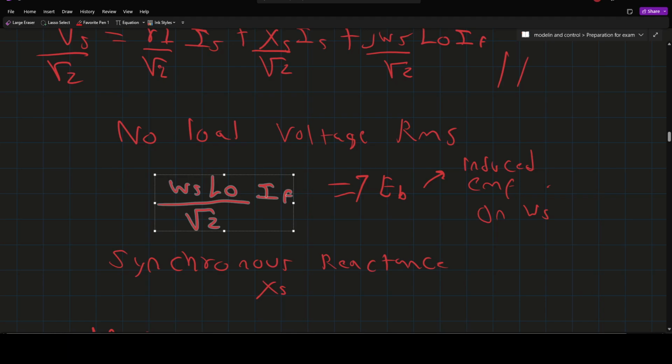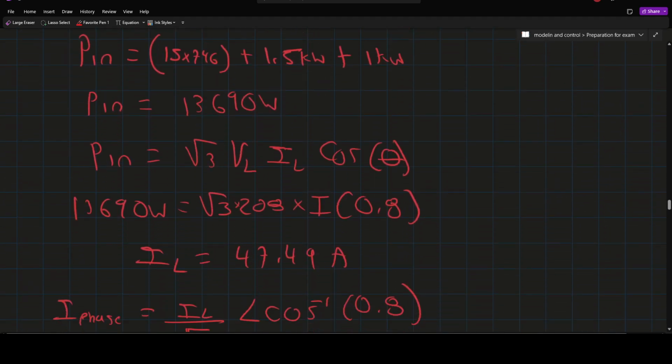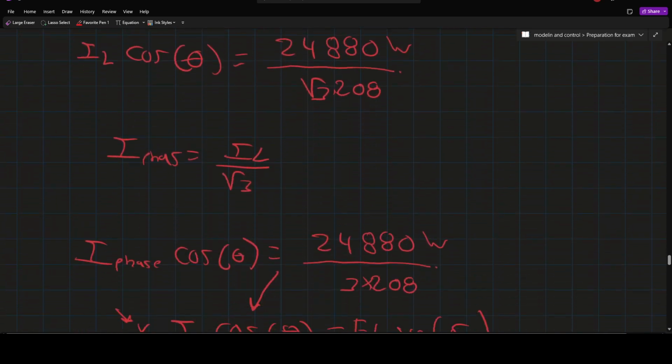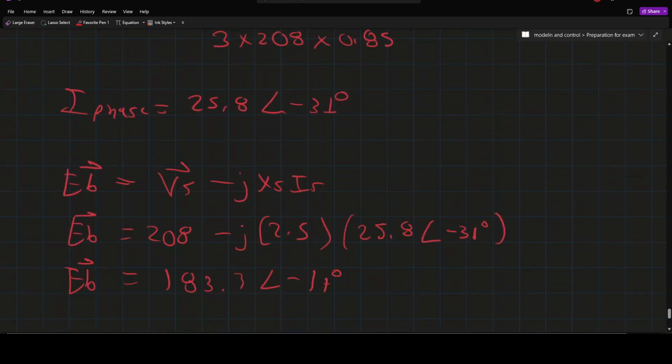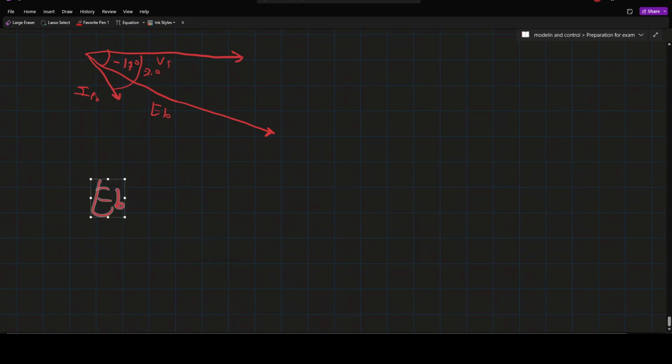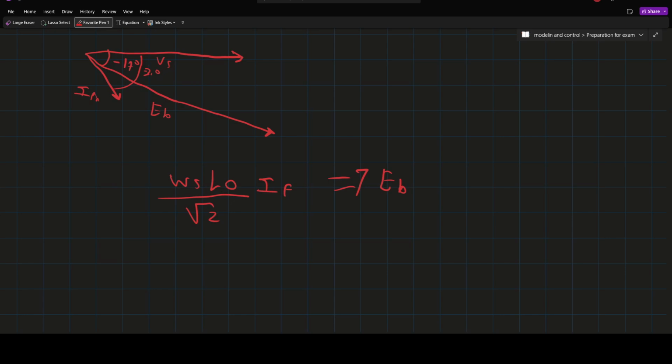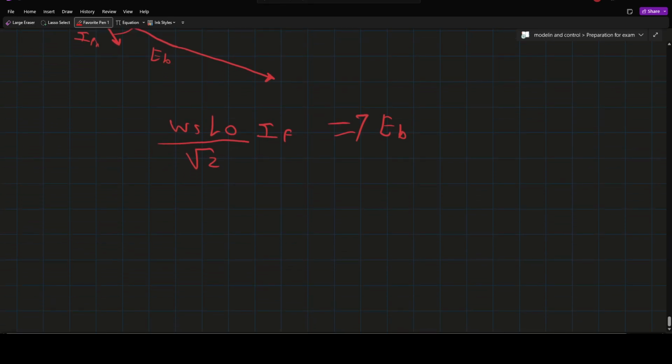So this is our formula for EV. Let me put it over here. So if our flux increases, our IF increases, that increases our EV. So what I'm going to say is that if our flux increases 25%, then our EV increases 25% too.